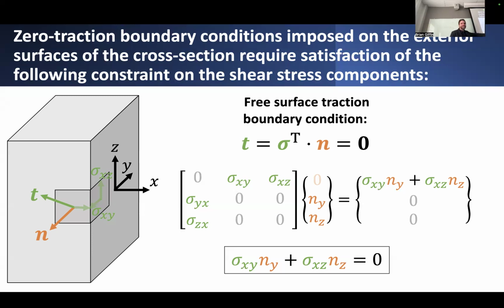If you remember how we defined this traction vector, the exterior traction that acts on this exterior surface of this bar, we could determine what these components of traction are by using our Cauchy stress theorem to relate the individual components of the stress tensor to the resulting exposed components of shear or traction that would result on maybe this surface or this surface. And it depends which components will be exposed on the resulting surface normal. So if you're looking at this particular surface, you would have to determine what is the resulting surface normal, let's say n, pointed in this direction, that would determine through this expression what the resulting components of stress are that